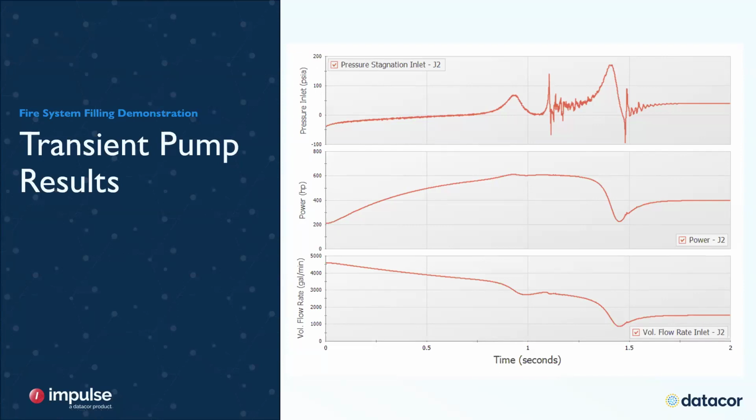Since we're using pipe filling and draining, we're not modeling the cavitation, but we can see that it would fall below the vapor pressure. In this case, since the filling is more important, that's a worthy trade-off. But there may be systems where the cavitation is a more significant driver of water hammer.